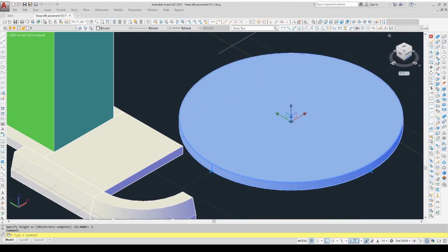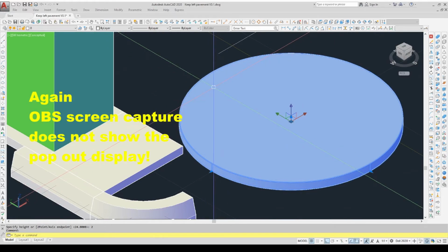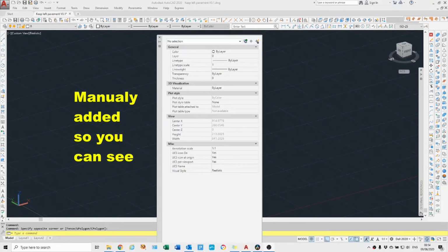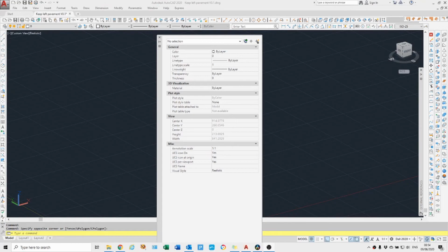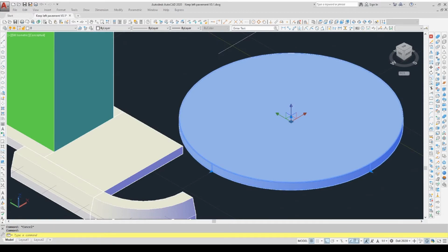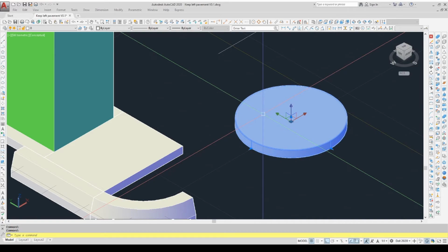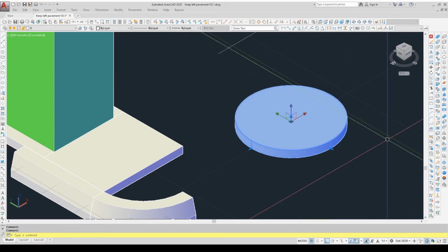And we can very quickly fix that because on my second screen I have another little side menu which defines the object that I've clicked on. So if I escape from that, it goes to general settings, but if I click on an object, it shows me the general information and data about that object in CAD. And it's showing there that it has a radius of 24. So all I have to do is change that to 12, press return, and hey presto, it's now gone to the dimension which I was after, which is 24.